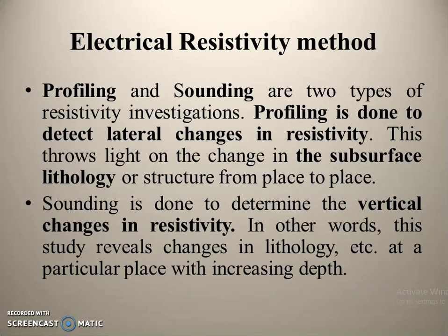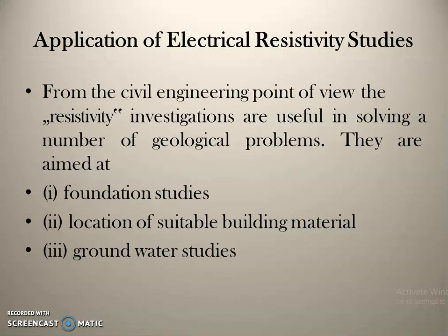In the electrical resistivity method, we have two resistivity investigations: profiling and sounding. Profiling is done to detect lateral changes in the resistivity. And in sounding, the vertical changes in resistivity are determined. This is the difference between profiling and sounding.